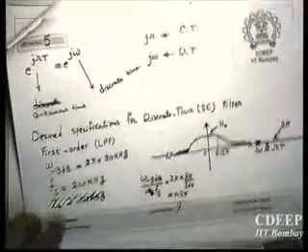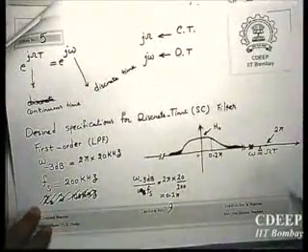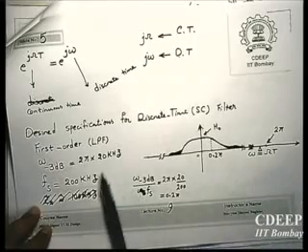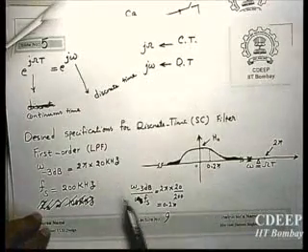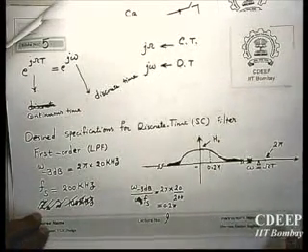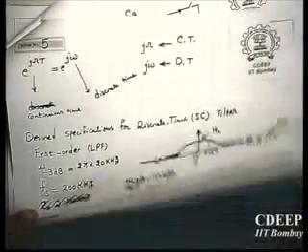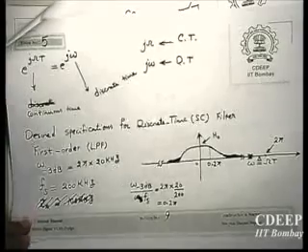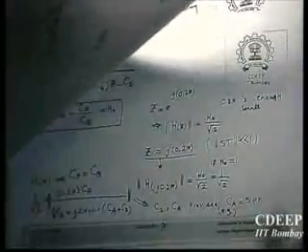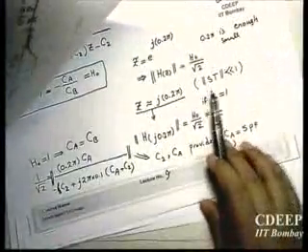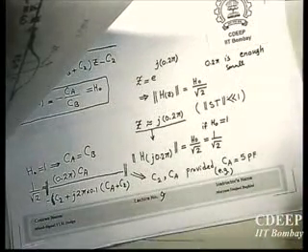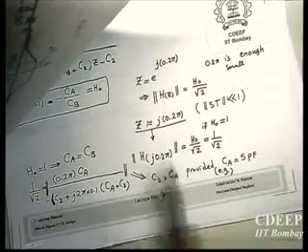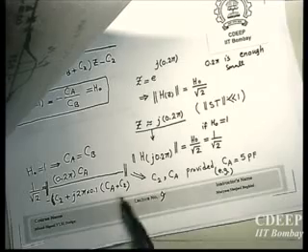Then about one example, it was just a first order filter with a given minus 3 dB frequency. Because omega T is much less than 1, the corresponding characteristic of the filter is easily understood by just mapping the relation between Z and S. And because the condition, magnitude of ST much less than 1, is valid, it's very easy to convert it into S domain.